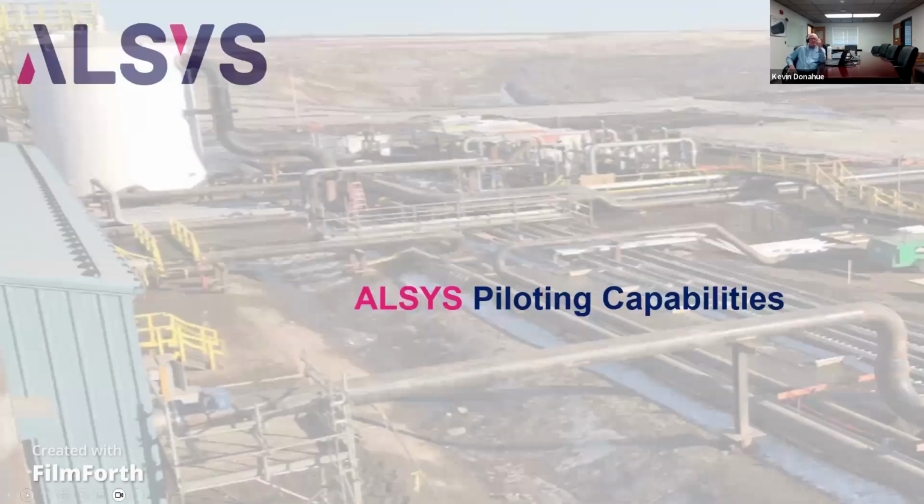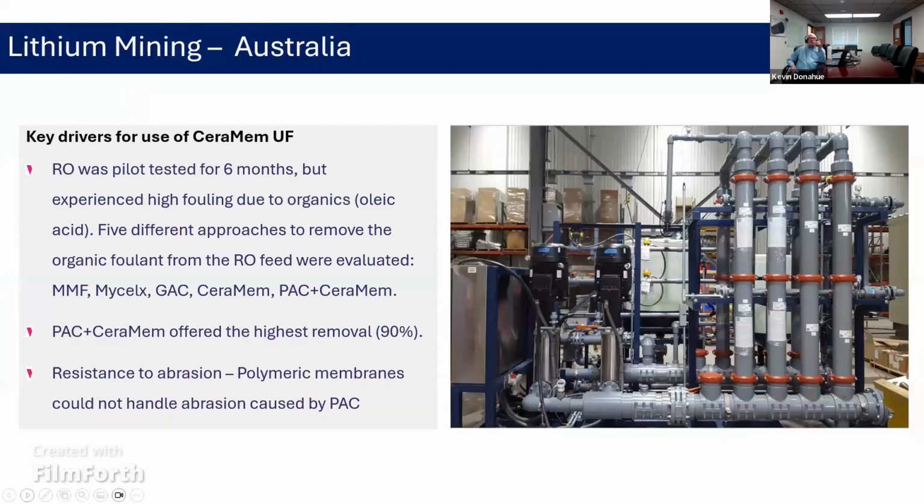Can we go back to that slide, please? Just one quick point I'd like to make here is that in evaluating the Ceramem membrane, the customer looked at other options as well. He looked at a multimedia filter, he looked at the Miselex technology, he looked at using just regular granulated activated carbon and a UF alone. The Ceramem with the powdered activated carbon was determined, after all that evaluation, to give the best performance because it gave the highest removal.